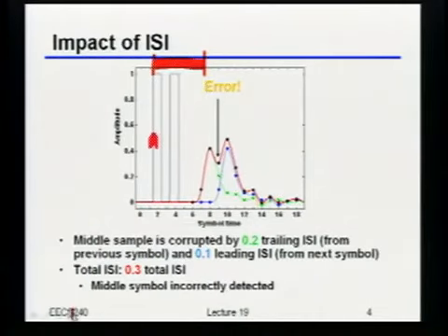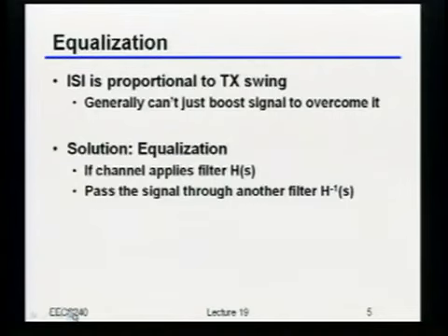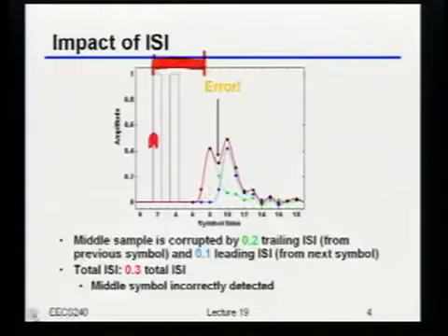Okay, so it turns out the way to solve this ISI, which again is just intersymbol interference, is a fairly well-known technique. I should mention one other thing. This thing here is really just a linear filtered version of the transmitted signal. That means that if I doubled the size of the transmitted signal, I'm just going to double the size of all of these dots here.